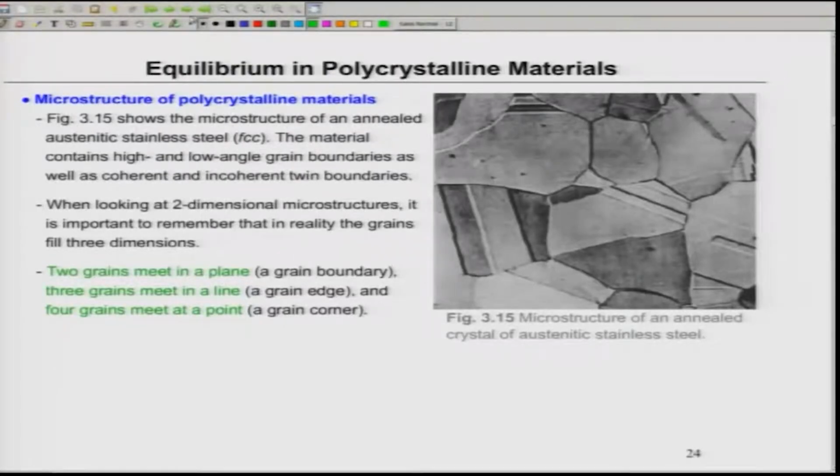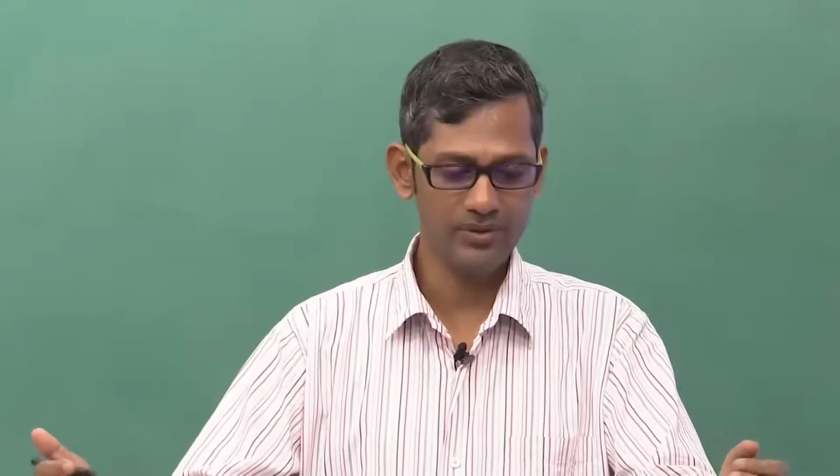Now, I have given you a fair amount of idea, although it is not possible to discuss all the high angle grain boundaries. Some of them are really very complex, but real microstructure consists of many grains. They are not actually only one boundary or two boundaries. There are thousands of grains in real microstructures, and each grain is oriented differently from the other grain. So therefore, the nature of the boundaries which all these grains will have with the neighbors will change based on the type of orientations they have, even chemistry also.